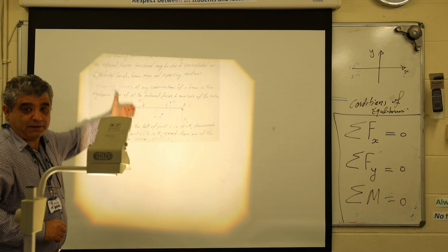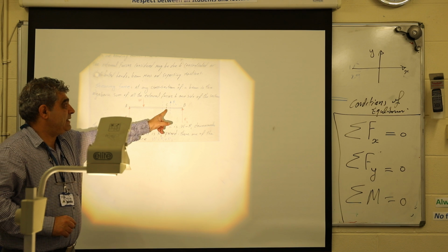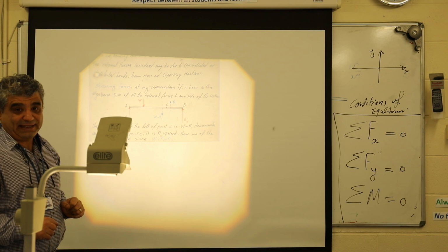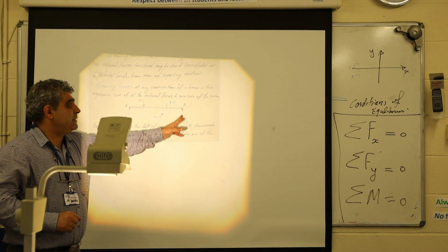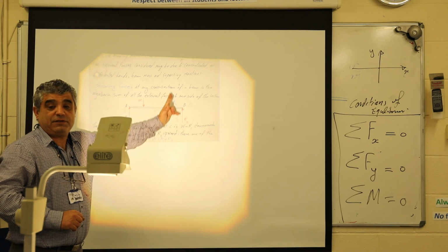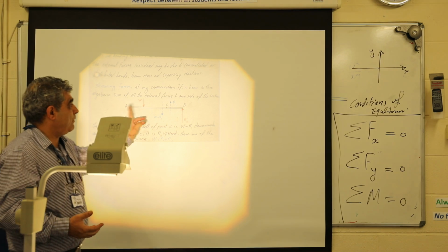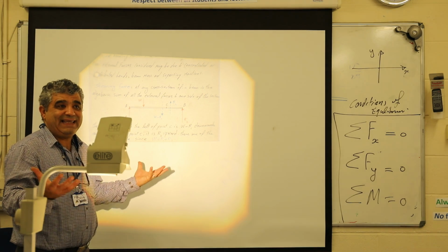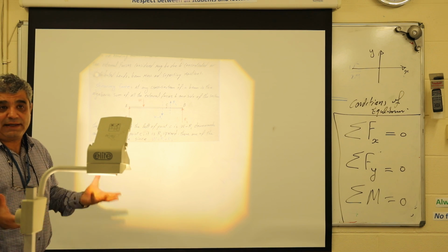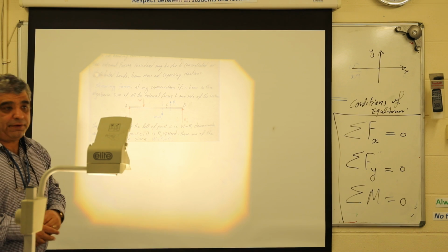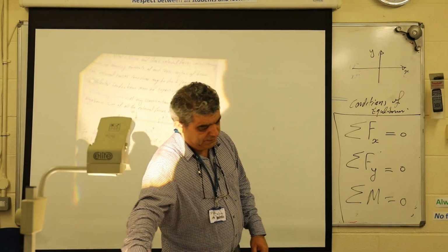One is forcing downward, the other one forcing upward, and that is the result about the point C we're looking at, yes? As you can see here, the result from R2 goes through this section of the beam, which we call R2. That's common sense, am I right? And ultimately R1 and R2 are acting in the positive Y direction and W is pushing downward, and they can balance via the condition of equilibrium. This is very simple and straightforward.